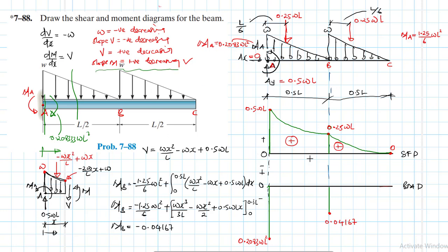Alright, so we have this value, and we know that our slope is supposed to be positive, right? And decreasing. So this is the behavior there up to, okay, we have this behavior like so, decreasing up to there, and it's the same behavior also, decreasing up to there, where our moment is just going to be equal to 0. Alright, if we did the section this side and moved the other side, we could also find the same value.